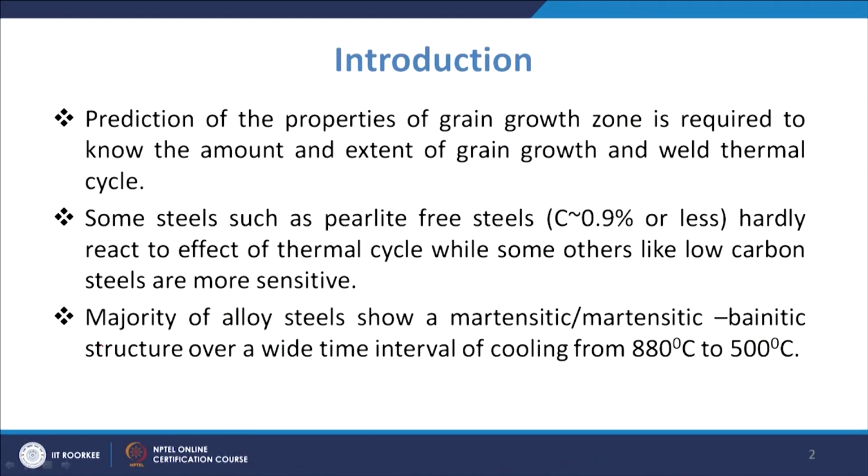So, knowing the weld thermal cycle, under what thermal conditions the specimen is subjected to, we have to know how much the extent of grain growth will be, and what its effect will be. Normally in the heat affected zone you will have an increase in strength in that region, but on some occasions we also see a decline in strength.